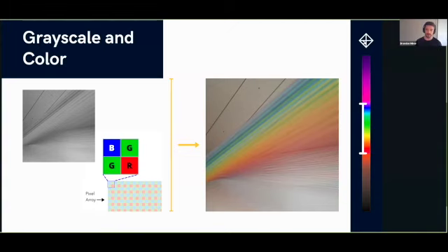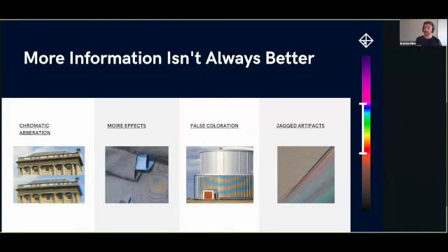So yeah, we get new information, we get more information, but we find that if we're actually putting this into computer vision, we don't get more out of it. More information isn't necessarily better here. And it's because of that debayering process. By the very nature of a Bayer filter, you're actually getting rid of the information not part of the filter. So you're getting rid of the red and the green if you're filtering out blue.